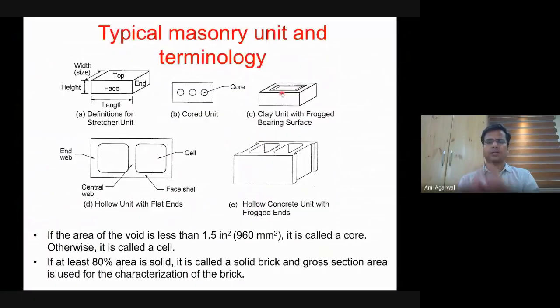I think you understand the concept, you're just not using the right words. It helps with developing a bond between the mortar and the brick, because if you have a perfectly flat surface, the bond between the brick and mortar may not be as good. So it helps with development of that bond, and also it helps provide the brand name.